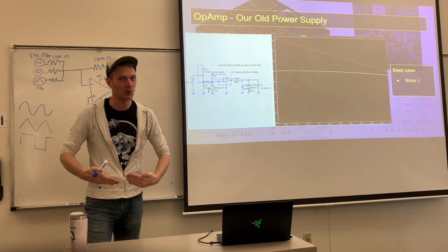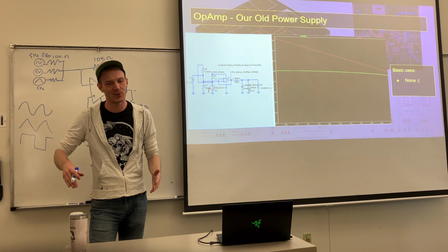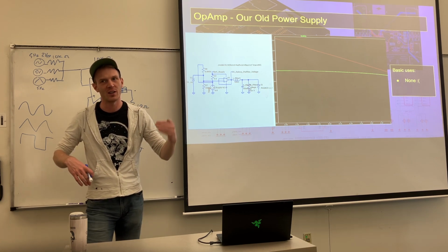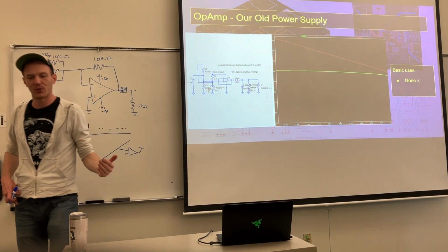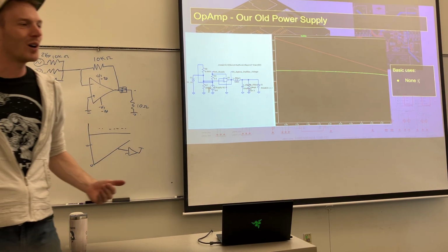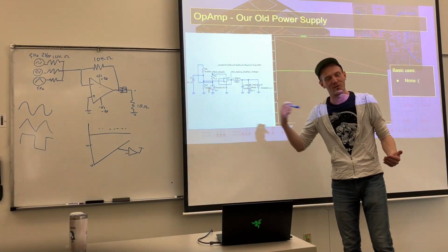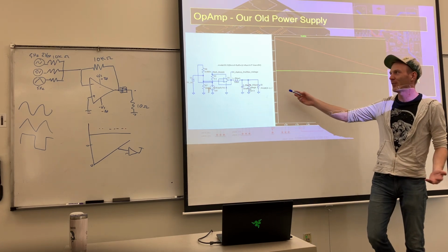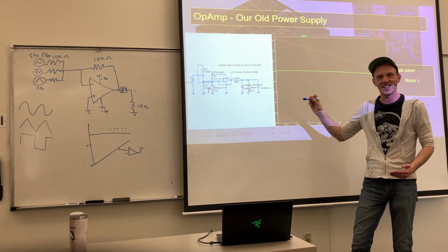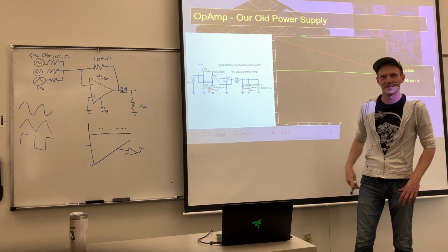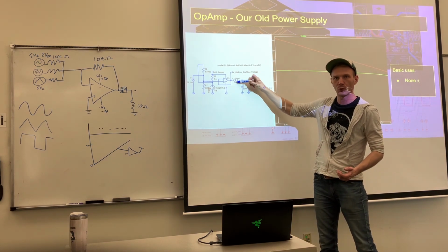A filter in signal processing is either a low pass filter, a high pass filter, or a band pass filter. A low pass filter passes low frequencies. A high pass filter passes high frequencies. The only frequency we want is DC, so we're trying to get the lowest of low pass filters. This filter basically says, if it ain't DC, I don't want it. If you're changing anything, don't. And we do that through, like we talked about, two different methods of storing energy.